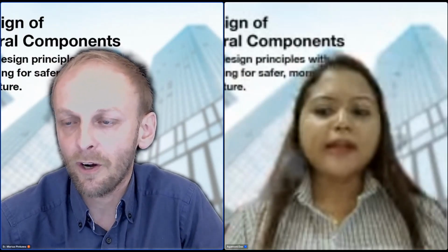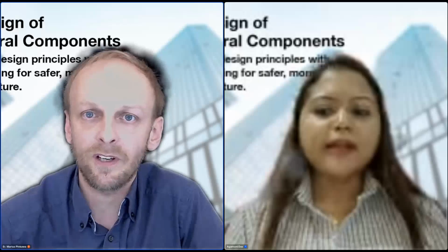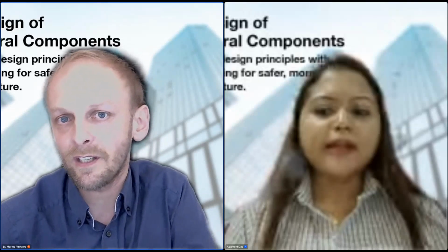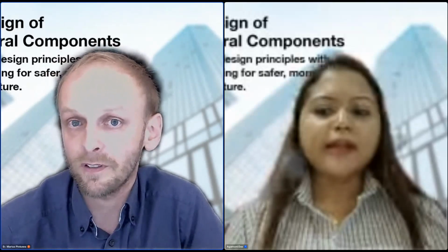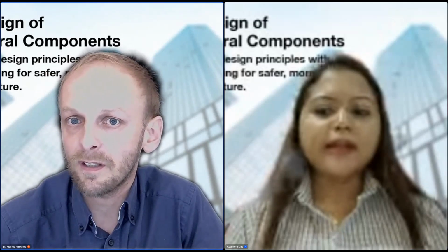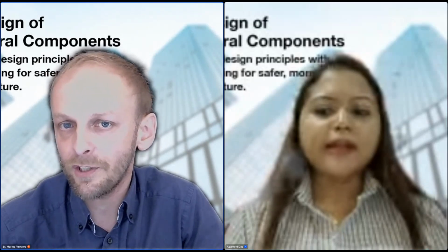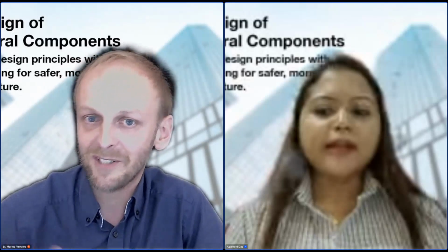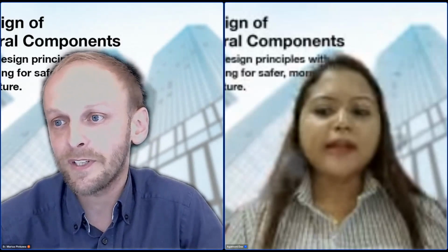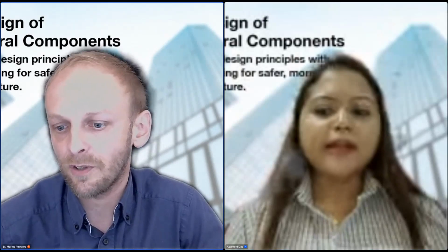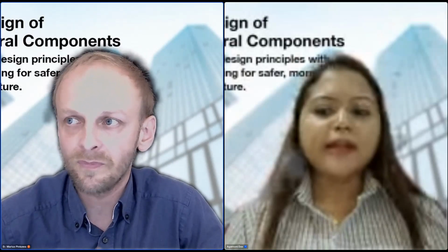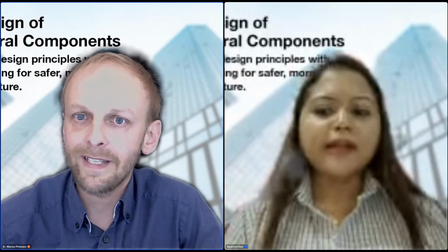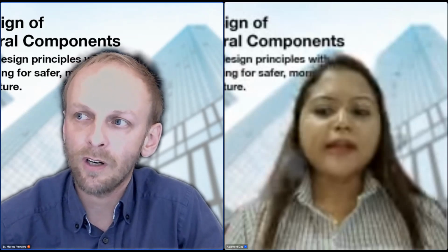Already for lower masses of the non-structural component, you will need a coupled model, because it depends on both the mass ratio of the primary supporting structure to the non-structural component, and the period ratio. So in the case of resonance, you will need a coupled model more often.